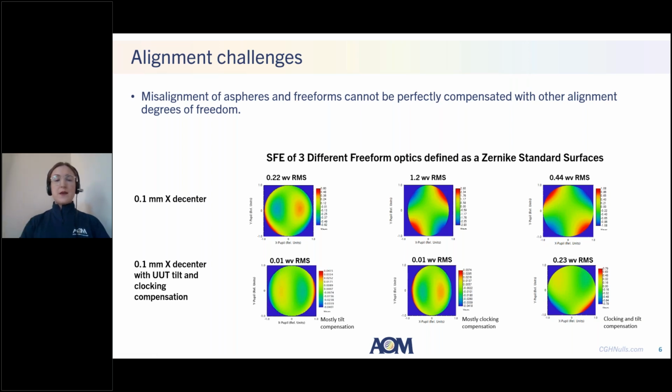So all of this is to say that we can't really trust using the optical surface itself and the alignment of that optical surface with the surface figure error as our feedback. What we need is some independent check that our test optic is aligned to our CGH, and we need that check to be relevant to datums that are important for our measurement. So as I say here, this residual error can impact the measurement accuracy, and it can also lead to erroneous manufacturing feedback. So we really want to avoid this, and we want to understand our alignment independent of this.